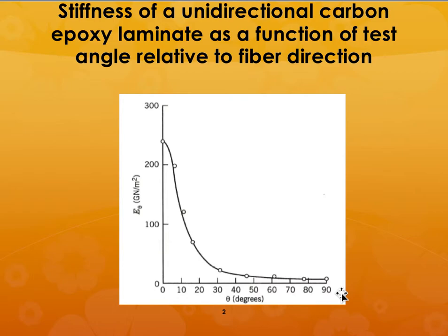So most of the time what we do is we have some fibers that are in the 0 direction, some fibers that are in the 90-degree direction, some that are in the plus minus 45 or plus minus 60, etc. So that you get almost uniform properties, because once you have the fibers all oriented in the 0-degree direction, you know that the composite is going to be a very non-isotropic material. So in order to overcome that, you combine the fibers in all different directions.